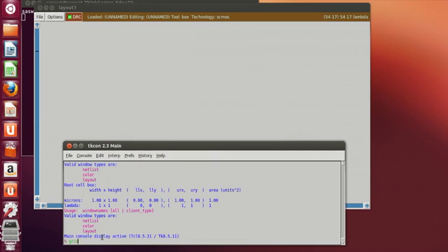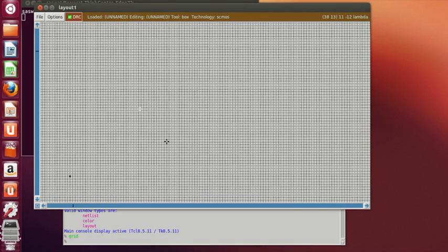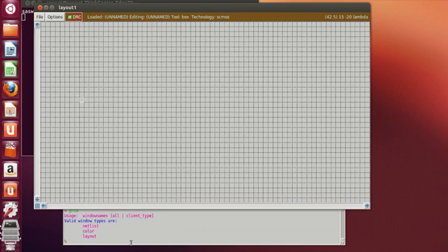Then type grid in order to grid in, then press Z to zoom in. Now in the NOR gate, the PMOS are placed in series and the NMOS are placed in parallel.